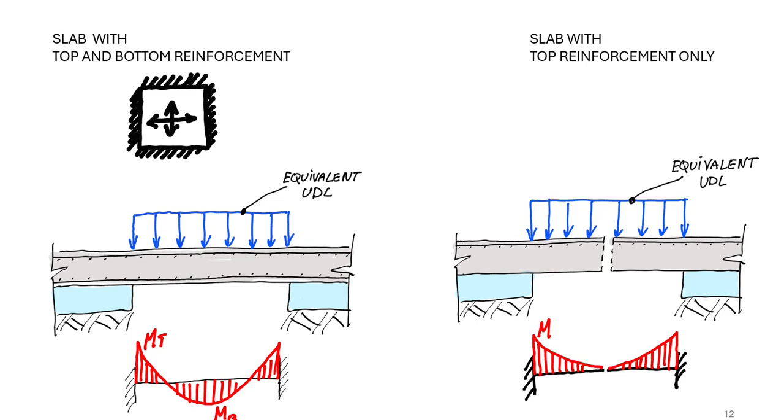So we may assume that our square slab is two-way bending, and it's fixed at edges. So we need to find internal forces, bending moments and shear forces in such a slab. But in the case of a square slab, it's quite simple because we can use formulas presented in engineering tables.